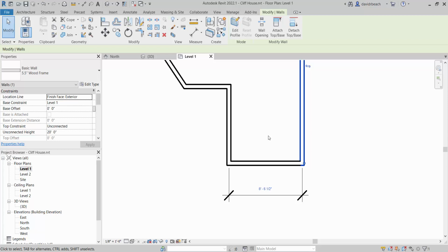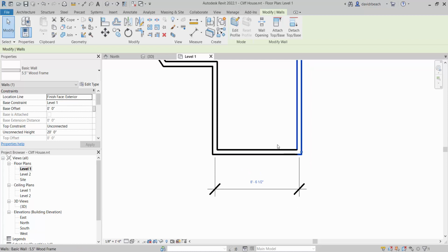It's not rhetorical. It's pretty simple. You take a tape measure, right? You've got your floor base, you're tape measuring that out. The dimension you're given is centerline to centerline. If it's a 5.5 inch thick wood stud wall, so it's 2x6 framing, how much do I need to add to each side so that I actually get the location of my walls? Because I can't really eyeball the center of a base stud, right? I need the edges of something.